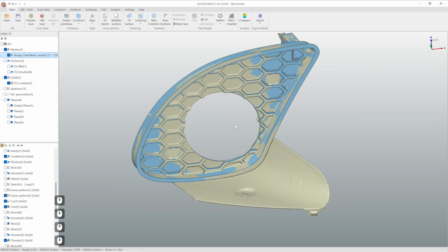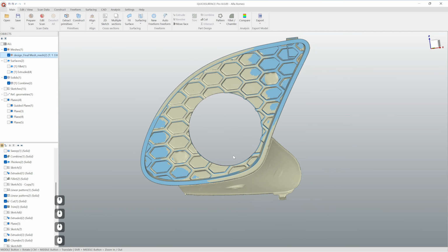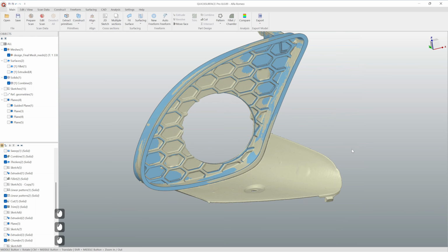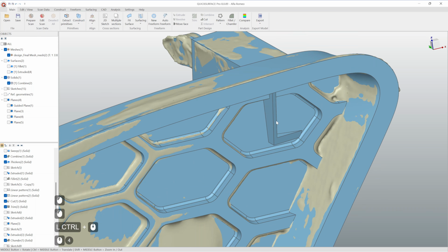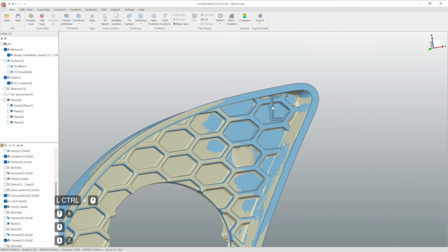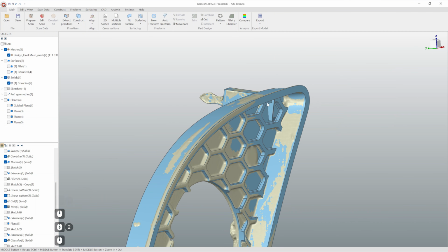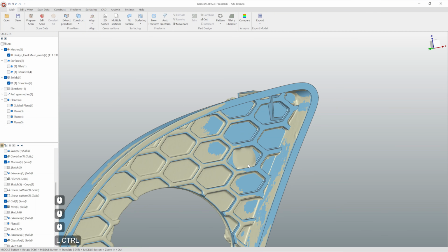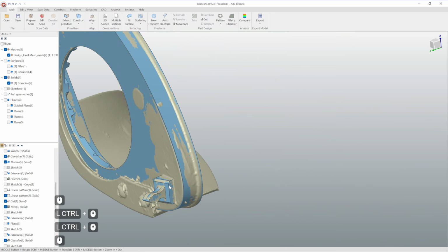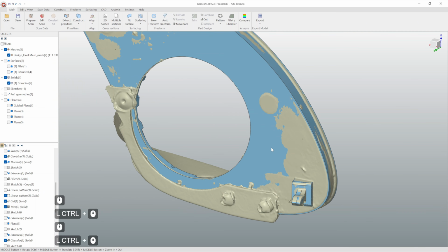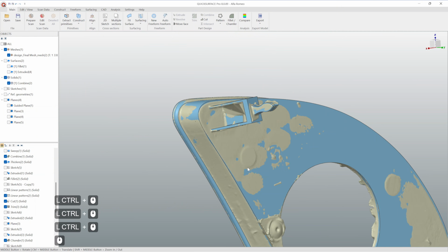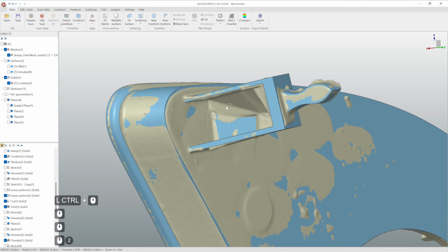And of course, as always, we have a lot of different options how we can do that. But before doing that, I just noticed that I actually failed here slightly. So I extruded this block slightly too far. The small one I snapped onto the surface. And this one I simply extruded through all.